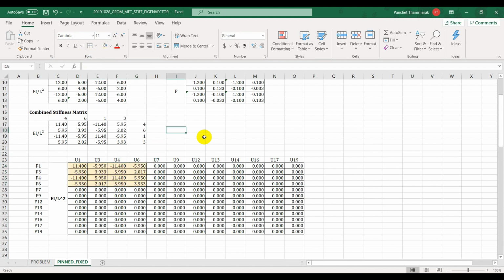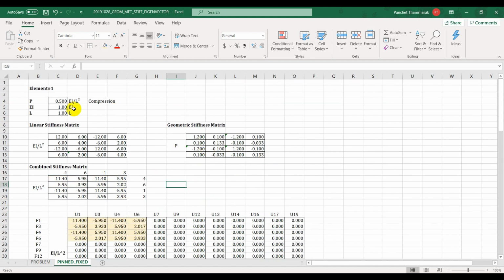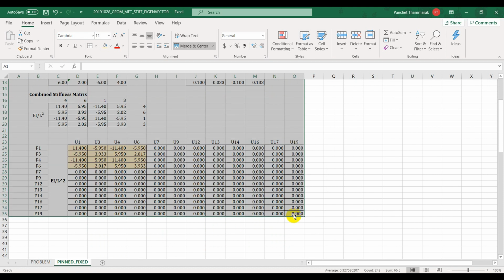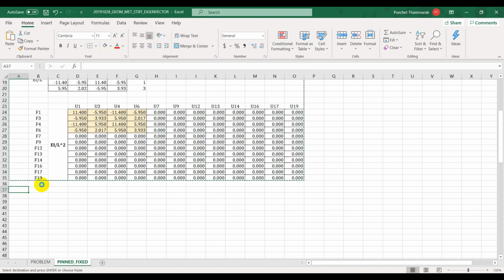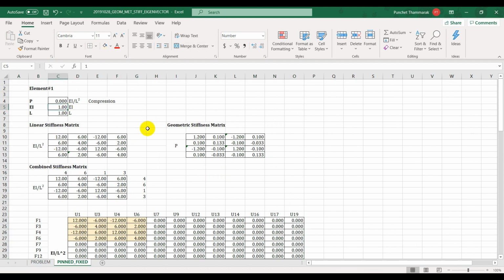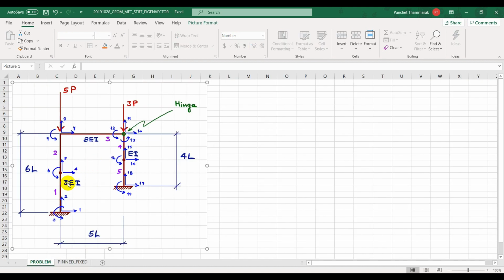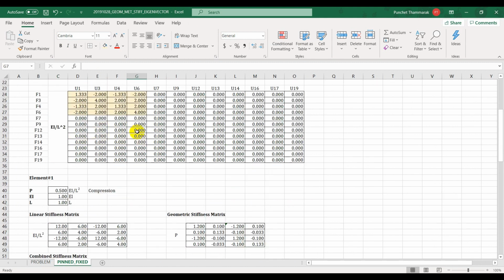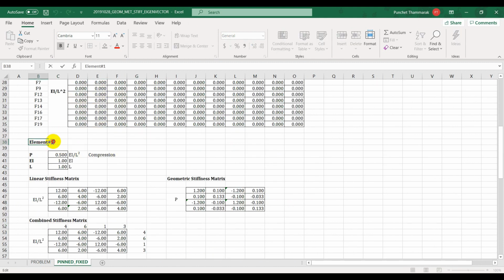This is for the element number 1, which is tied up with the parameter we input over here. We have to change that EI, right? We haven't done that. We will go seek for this one. So just assume the 0 first. The EI is 3 EI, the length is 3 L, so you drop in the 3 and the 3. Done.